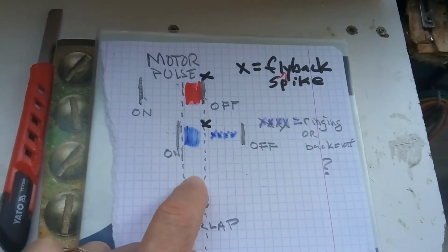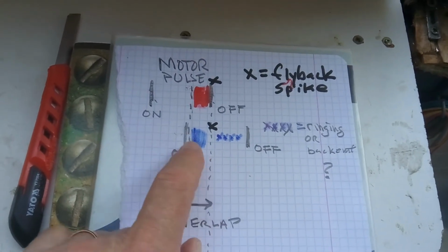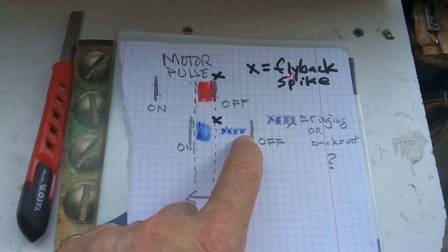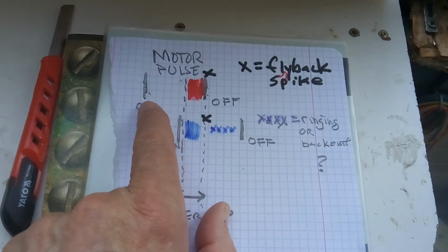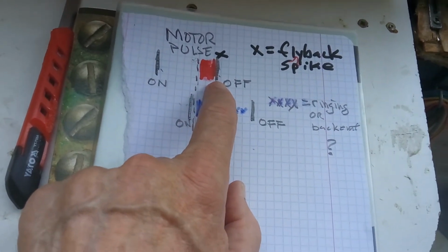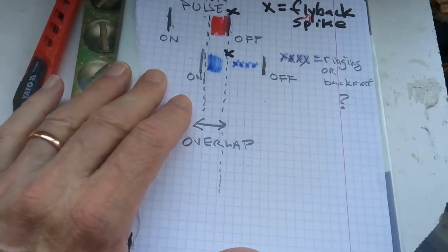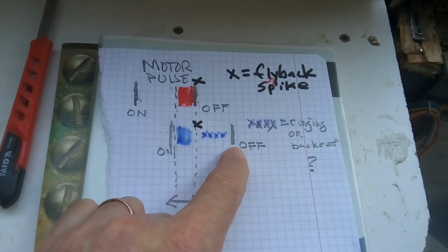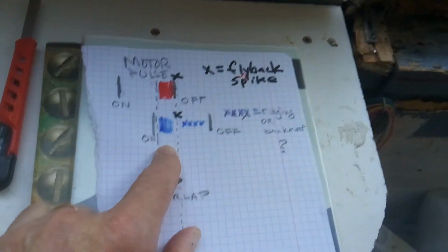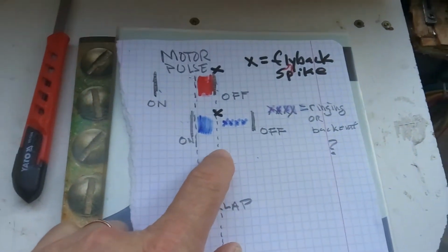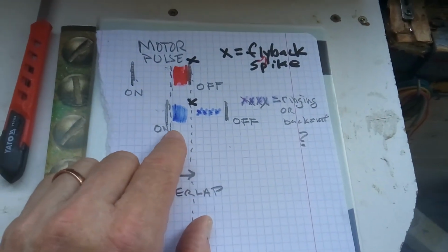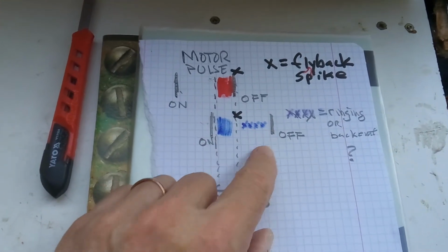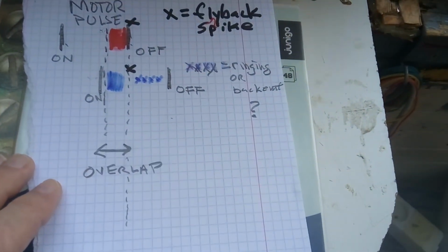Now, also, this is occurring at the peak period when it fills, because if you look at a scope and a motor coil pulse, it's up there at the peak period of the sine wave as the magnets sweep by. So you're doing this at the peak period too. If you wanted to do this with Arduino or something, that's what you look for, the peak period to sense when to do this. But that's another story there.